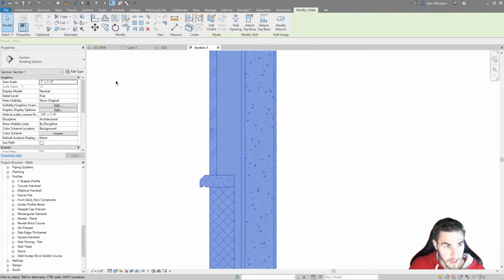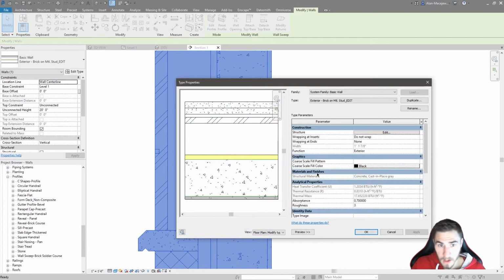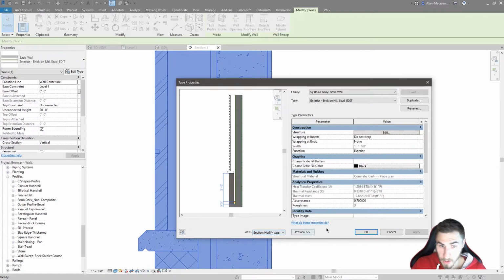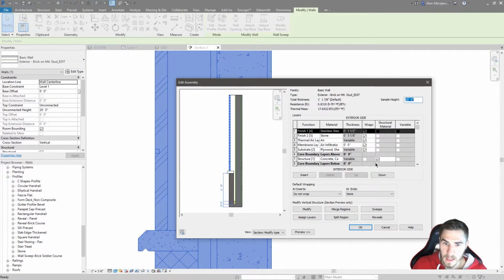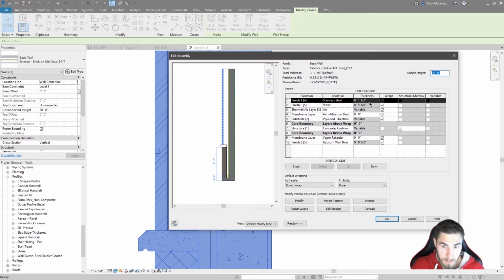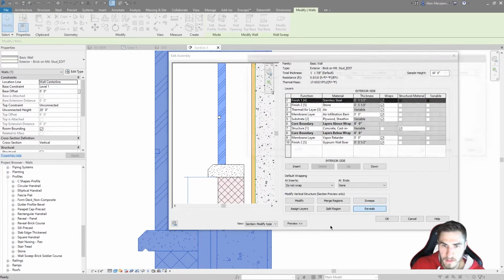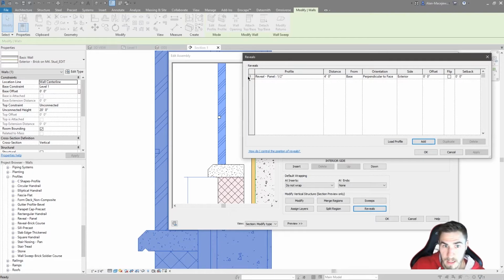So with that said, we can actually come back into our wall and place these however often we want. And so the cool thing about not only reveals but also sweeps is that you can have as many as you want throughout the whole wall, and you can place them wherever you want based on anything else. And so we have it there. It's at 4 feet. We've got our reveals here, and I can add the same one again.